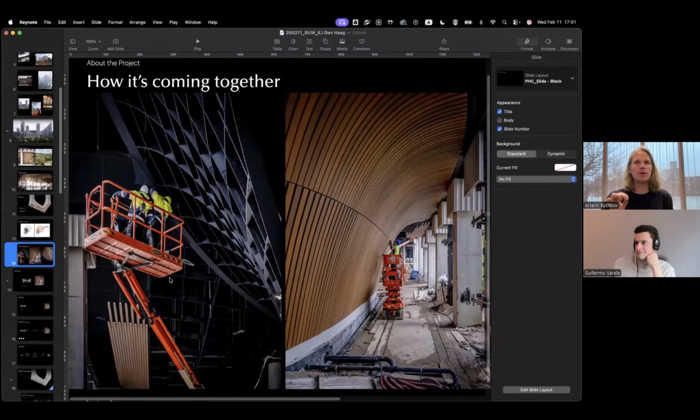There is a very, very precise model. I don't remember the name of the software, but it's not Rhino. It's something used in the later phases, like a BIM model, let's say, with all the planks modeled and the back structure modeled. Then this back structure is CNC milled, put together with code and everything, like this parametric bench, as I call it. The planks themselves are manually placed, following this model but not precisely. In the end, the planks will not correspond to any of the technical drawings per se, because they have to decide on site where to cut them.